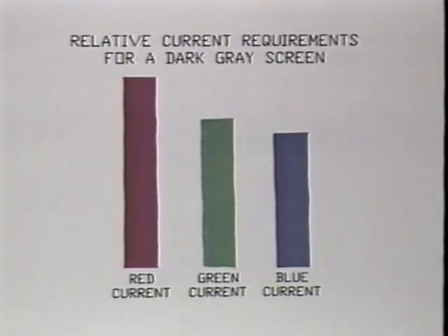Next, turn the red bias potentiometer back up until a medium brightness red pattern appears. We start with the red beam since it requires the most current to turn on and will match the other 2 beams to it. By starting with a medium bright red beam, we are setting all 3 output transistors near the center of their bias range, which will produce the best results.